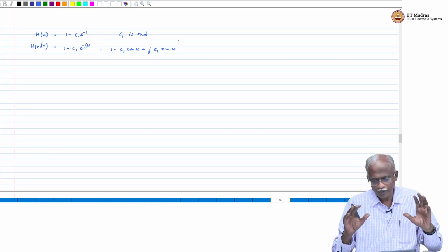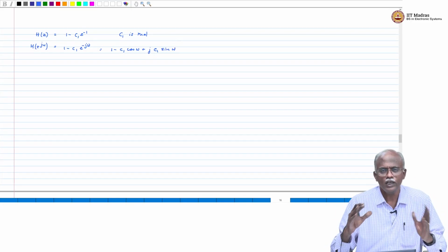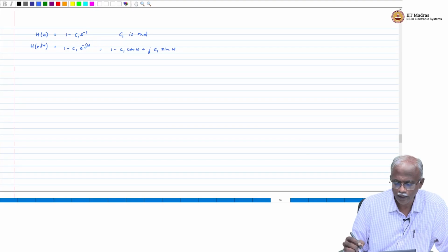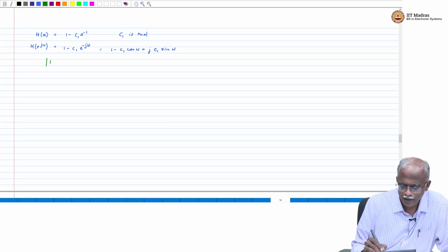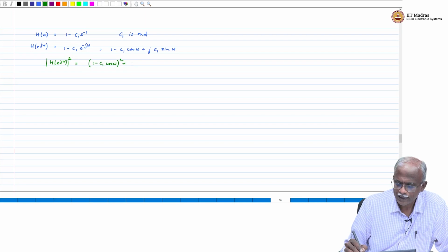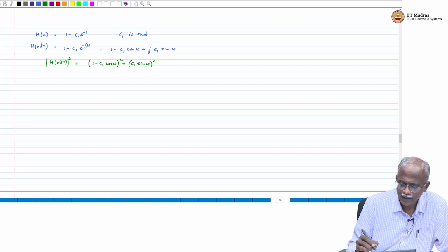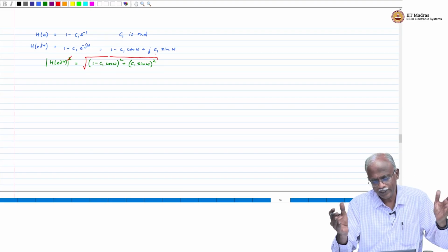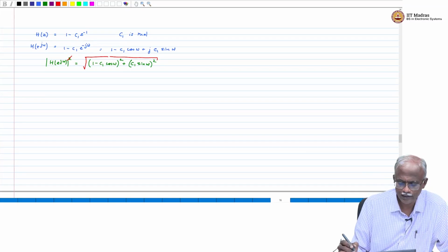Okay, this particular segment of the lecture is going to involve a lot of trigonometry, so I will write it down, but do take time to make sure that you are able to verify these results. The magnitude squared of H(e^{j omega}) will be (1 minus C1 cosine omega) whole squared plus (C1 sine omega) whole squared, and if I want only the magnitude, then this will be the square root. So you now know how to get the expression for a first order term.